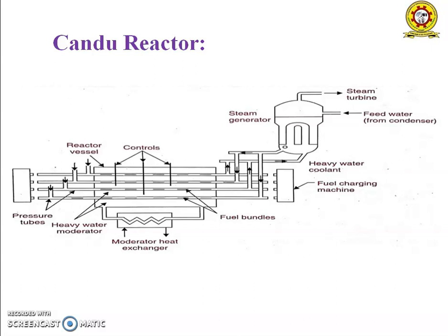And the disadvantages of the reactor are, the cost of the heavy water is very high. Heat exchangers must be leak proof, which results in a higher initial cost. A very high standard of design, manufacture and maintenance is needed, because if any of the tubes gets a leakage, it should be replaced. The reactor size is very large, as power density is low when compared to other reactors.